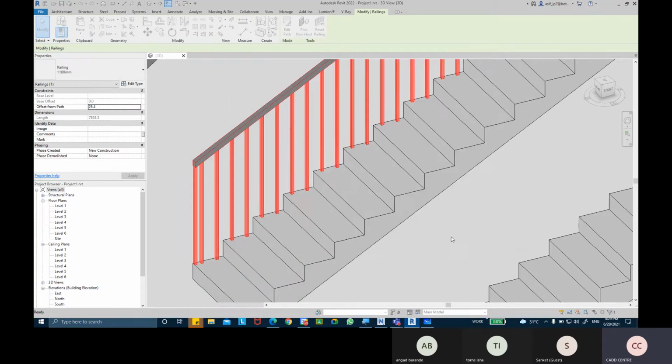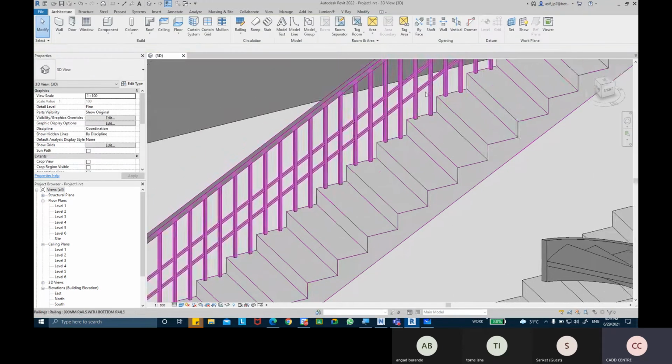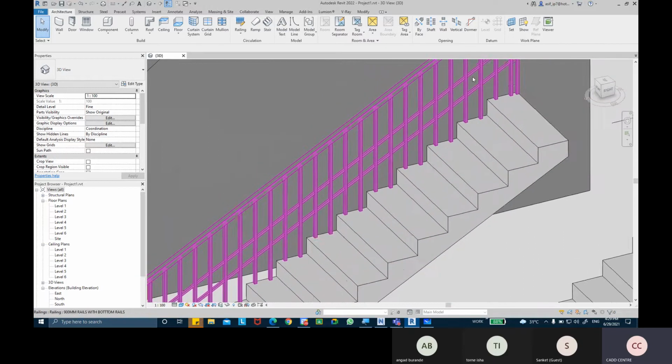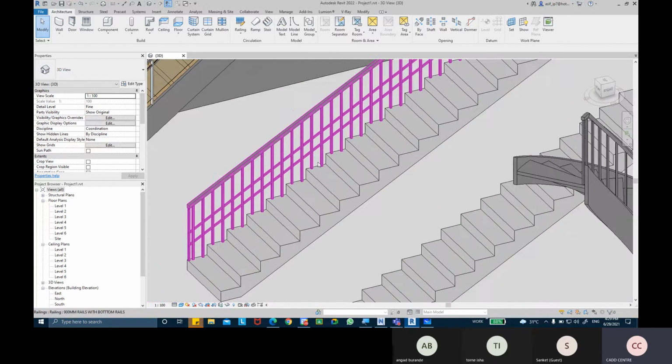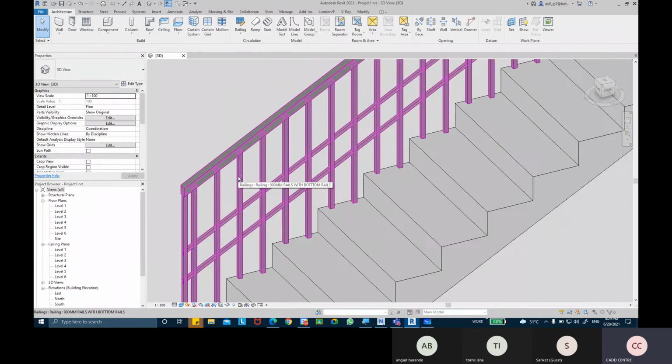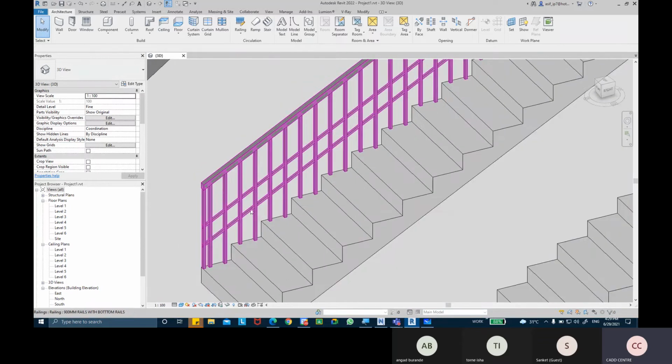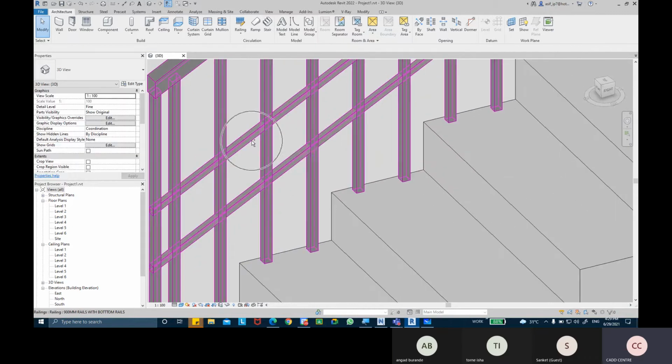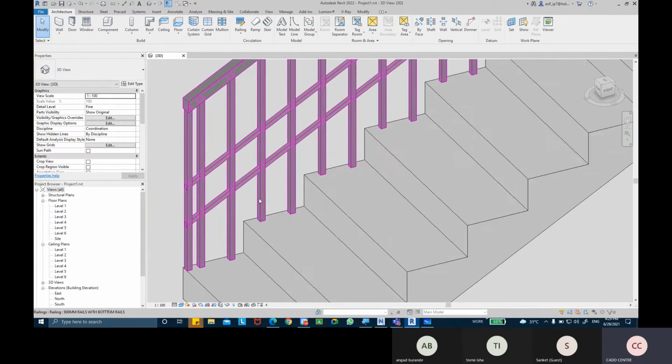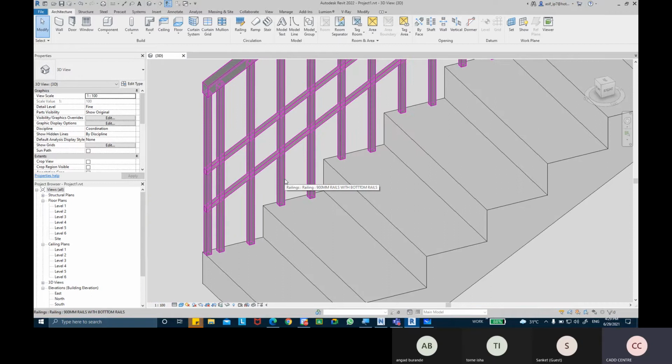Meantime, if I click on apply and click on OK, you'll see that we have these bottom rails being added in the railings. So earlier we were just having the top rails and the balusters, and now we have the bottom rails also being inserted in it. You can create your own profiles also of the bottom rails, and you can insert them as well. Generally, we have two profile shapes that can be inserted in the bottom rails. One is the square, or one is the circle, or you can add the elliptical ones. Rest is all okay basically. There you can try the other ones basically.